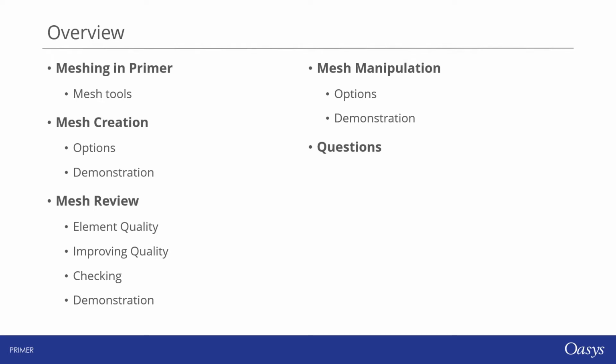Next, I'll talk about mesh review, how you can check your element quality, improve it, and I'll have some demonstrations of them. And then finally, I'll talk about mesh manipulation and the options available, such as removing or adding holes, swages, splitting, and even remeshing. And I'll have some demonstrations of them. And then at the end, I'll try and answer your questions.